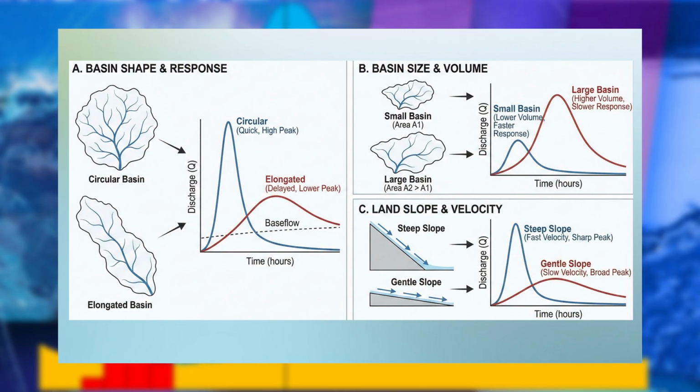These also include the slope of the land surface and main channel. Features such as the shape and size of the watershed, slope, elevation, drainage density and the nature of the valley impact the hydrograph. All these elements collectively control how runoff is generated and drained to the outlet.